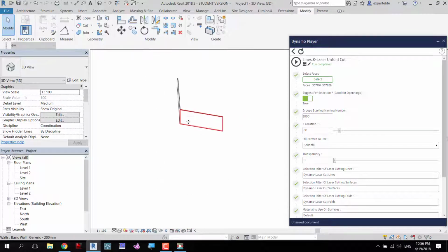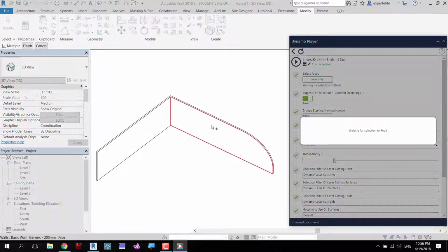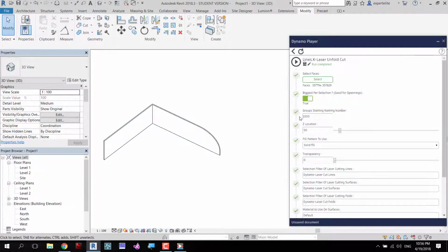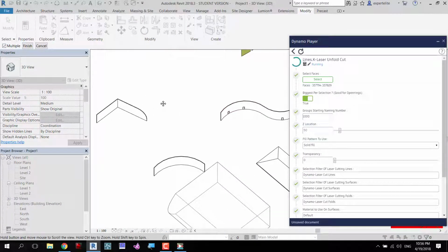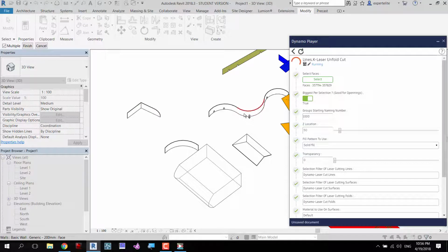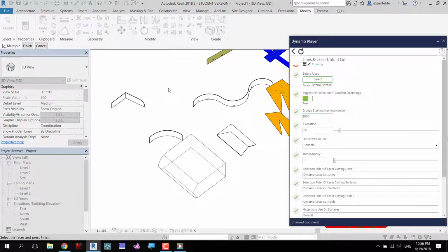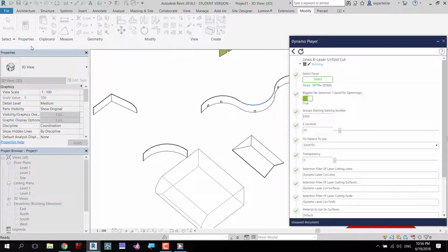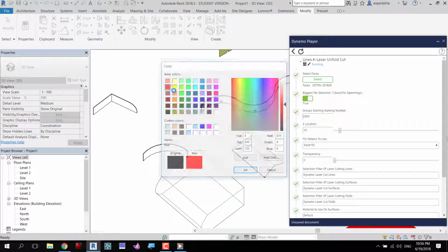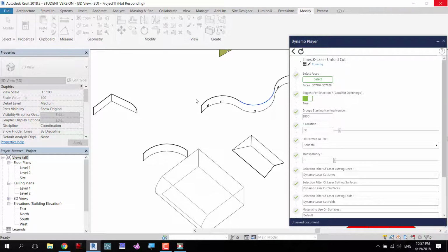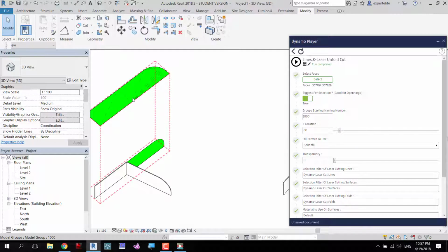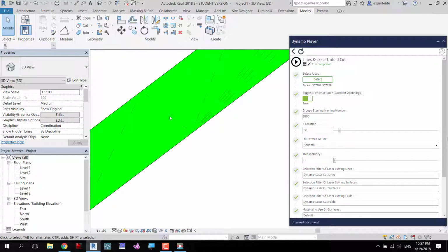So I've mitered them, and you can choose whether the interior or the exterior. It's up to you. So I chose those, and I play again. And now the question again is just choose any reference face. The meaning of this is if you click on there, the faces will justify to the right side. And if you click something there, they will justify to the left side. It doesn't matter. Simply anything works. Now finish and choose the colors. And here you go. You have your face, you have your full face, and there's the unfolding here.